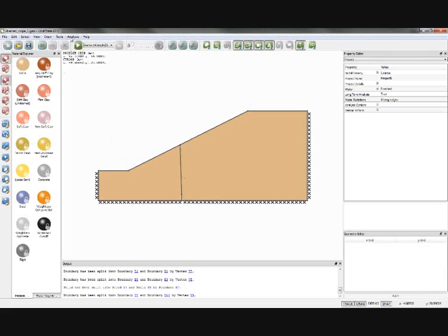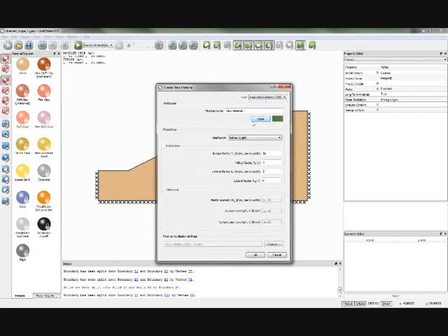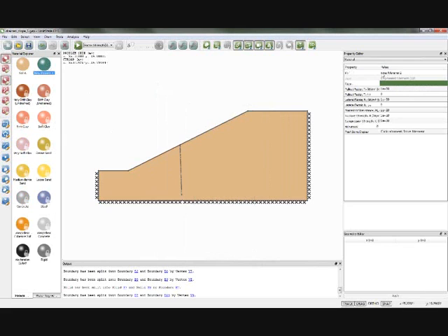In the software, if I create a new material, we have what's called an engineered element, which is something that we can use to model sheet pile walls or soil nails or geotextiles. So I'm going to pick a rigid sheet pile wall, which is fairly basic. All the properties are set by default, so I just click OK. And this new material here, perhaps I'll call it sheet pile. For clarity, I can drag and drop that onto there, and that will behave as a rigid inclusion in